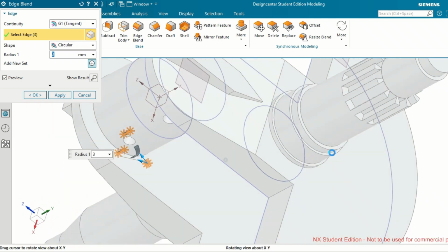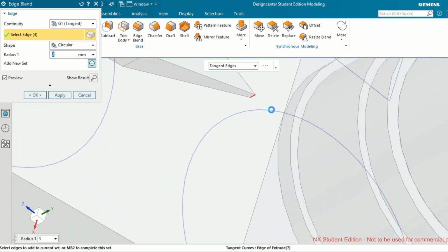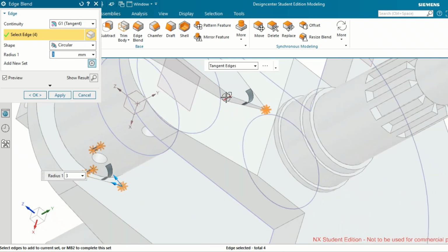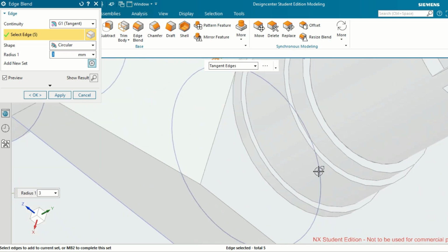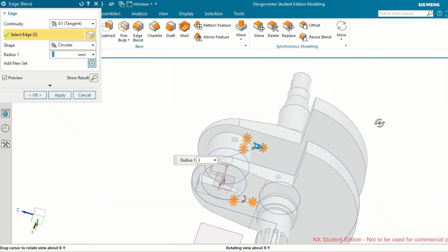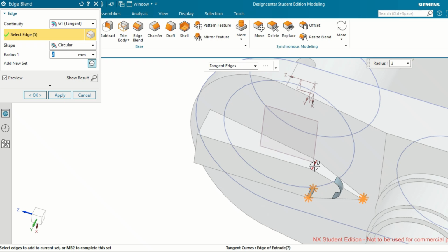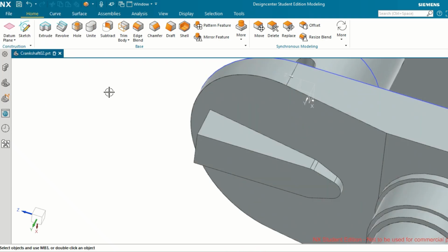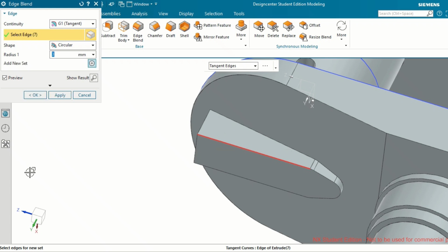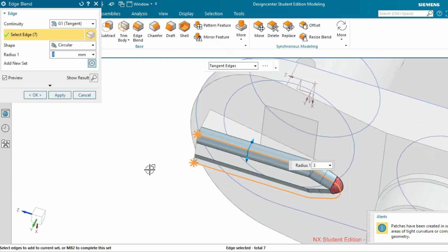This is the way to apply holes, and we should do it last after creating all the extrudes and blends. Okay, and here also you'll see one more thing. I gave edge blend at 6 places, both sides, and I'm going to give edge blend now one more time at 2 places. You see, only this 3 mm, it's not taking it.